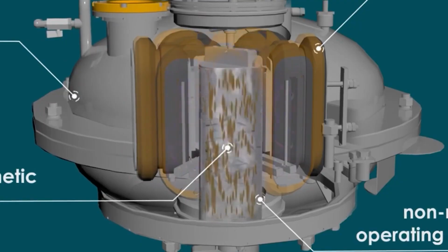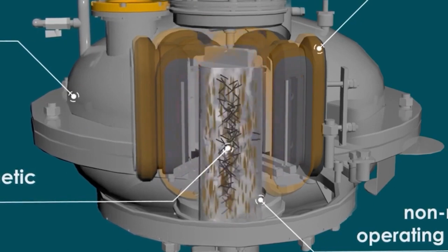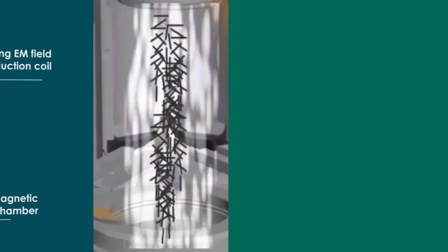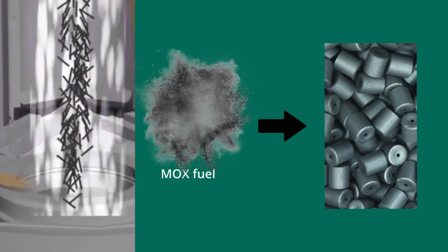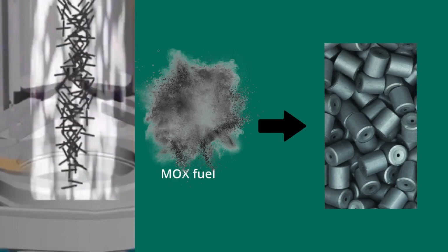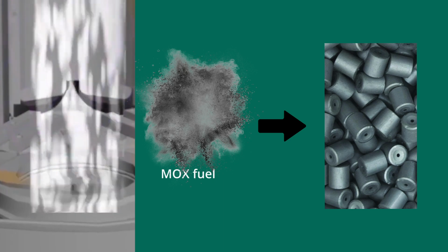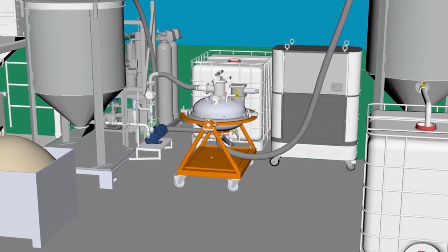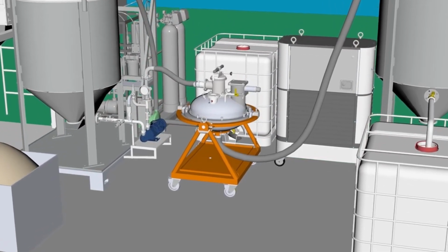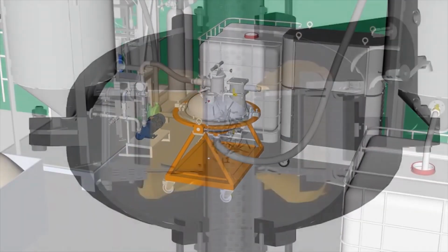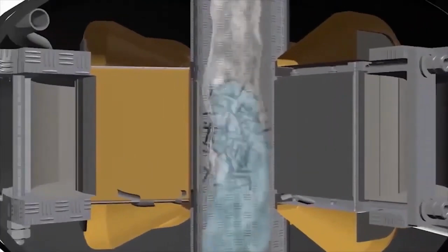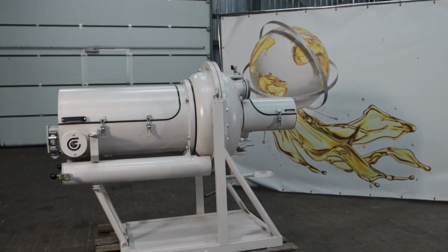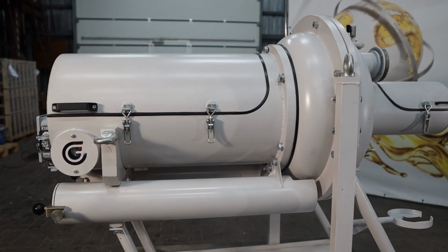Magnetostriction of ferromagnetic particles, etc. The comprehensive effect of the above-listed factors ensures rapid dispersion and homogenization of initial powders, which means achieving the high-quality molding powder of MOX fuel for production of fuel rod pellets. Given the occupational hazard to operating personnel, automatic mode is used for feeding of initial constituents and ferromagnetic particles, as well as for cooling and discharge of finished molding powder.